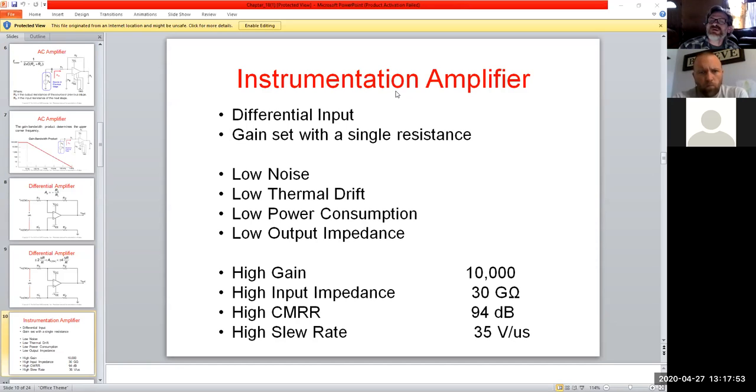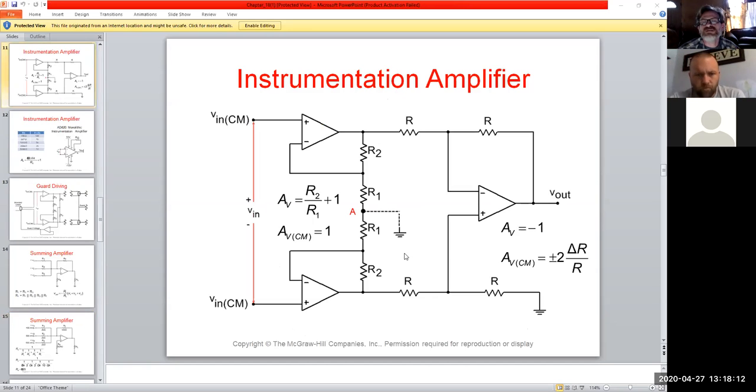So it means we can handle quite a lot of current with this as well, right? We got a high common mode rejection ratio and 94 decibel swing, basically giving us our bandwidth, right? And a slew rate of 35 volts per microsecond. Remember in a graph how that all looks out for us. Basically, I mean, we get it. It's huge.